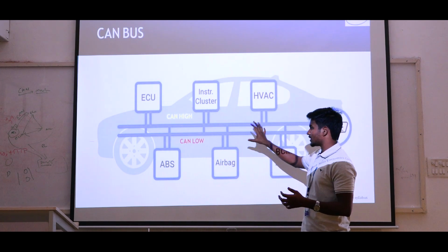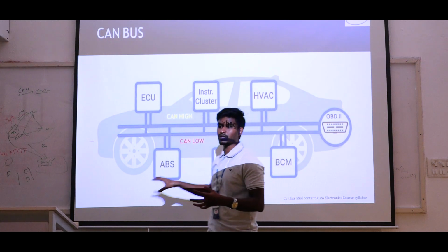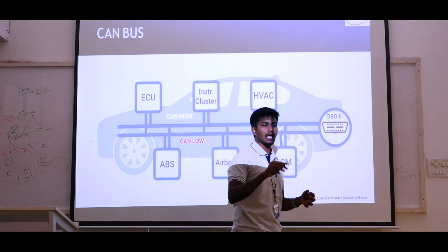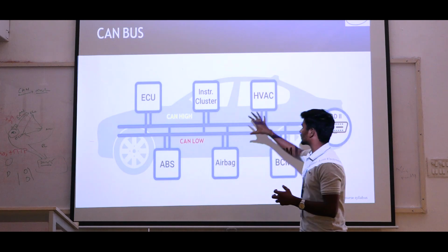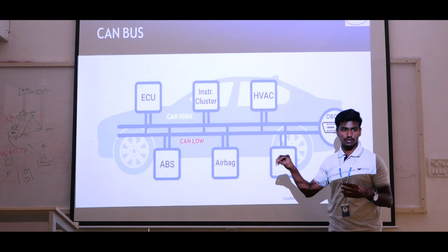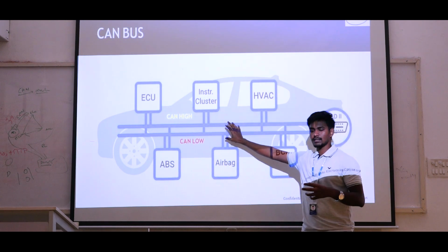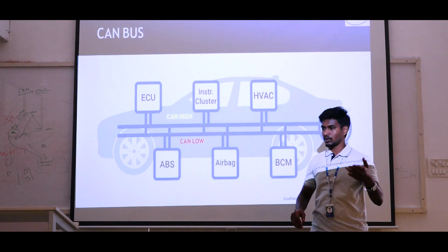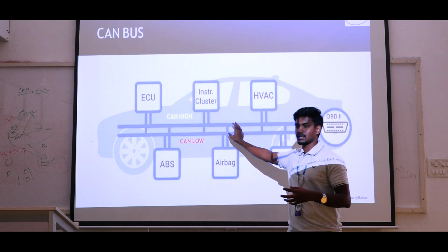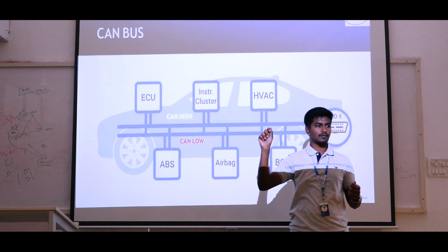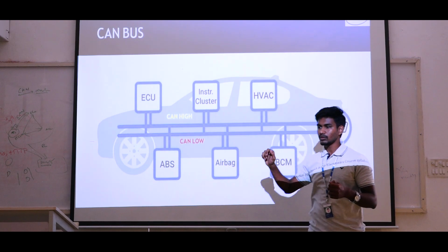Our major topic is how these ECUs are communicating. That is called IVN communication, in-vehicle networking communication. For example, now we have 5 ECUs. The protocols are CAN, another one is LIN, another one is FlexRay, another one is Ethernet. So why are we focusing on the CAN protocol and not selecting Ethernet, FlexRay, or LIN? This is the concept.